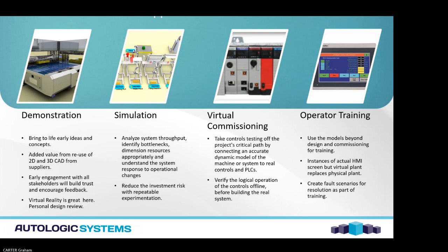There's your PLC, your HMI screens that the operator interfaces with, and it's not the physical plant, it's the virtual plant, but you're very much testing and interacting with instances of the software that are going to go to site. That means we don't need possession of the plant to run our training scenarios and our faults. We can put our virtual plant into fault, and we can ask the trainees to recover those faults. It's an excellent space for that.